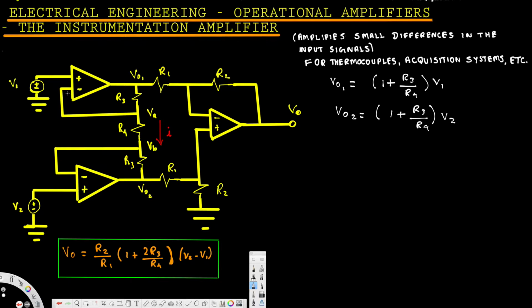And we know that for an ideal op amplifier, there's no current flowing in or out of the positive and negative terminals, so the current is 0 right here. So whatever the current going through this one should be equal to I, like I is everywhere. This is in series, so I must be equal everywhere, right?